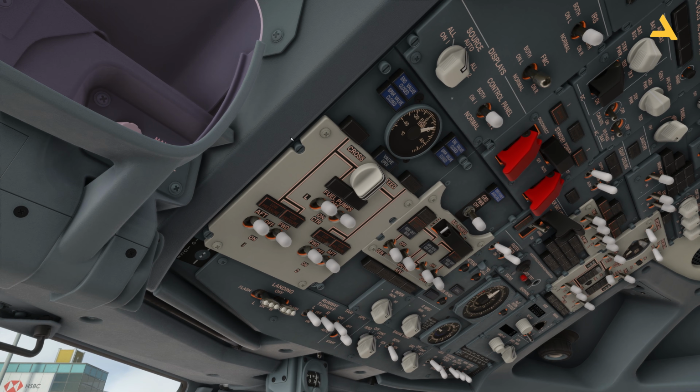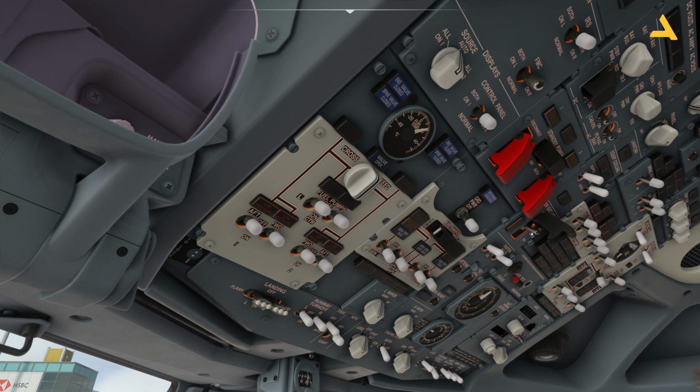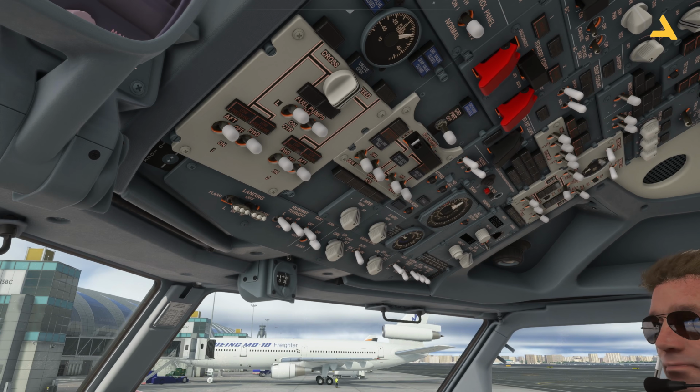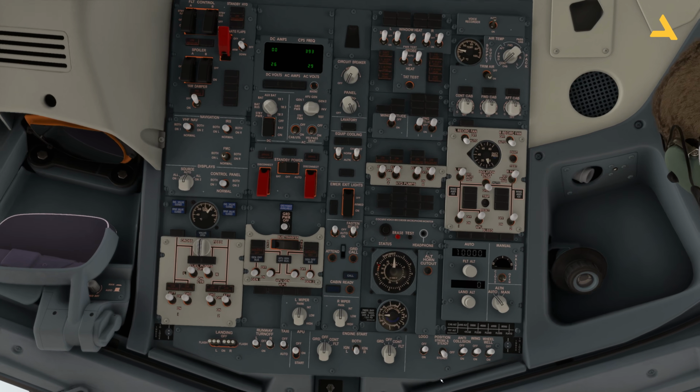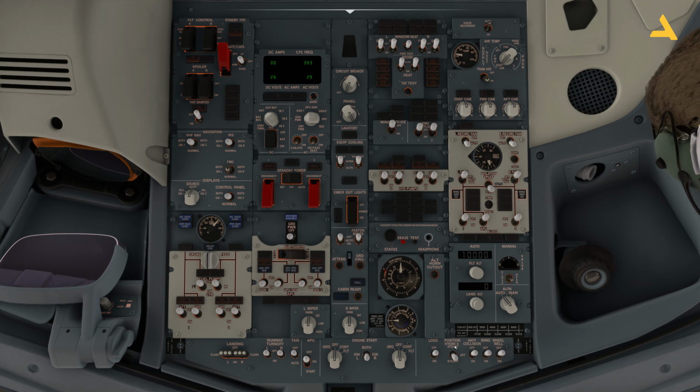That's it. Now you have this control for the emergency lights. So just arm it, move it down. If the switch doesn't work by clicking it, just hold it with your left mouse button and move it down and close the lid. That's it. Now there is this light, which is position, strobe and steady. Just move it to steady, and that's it.